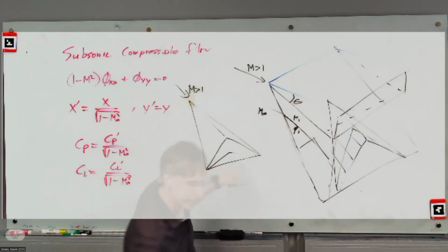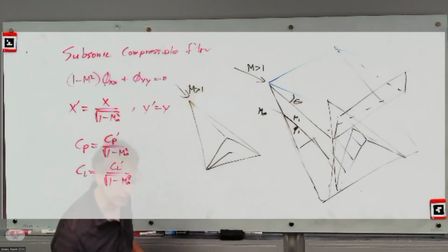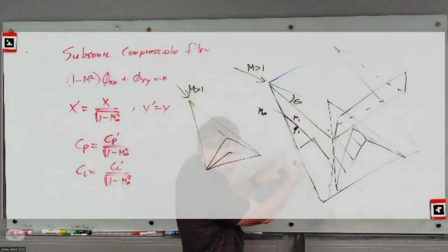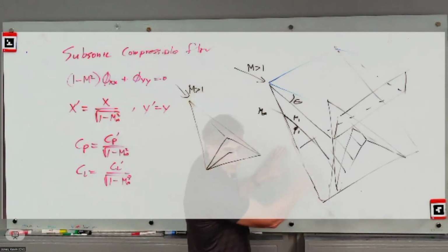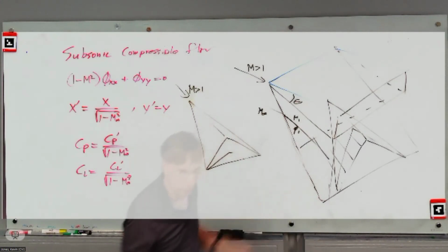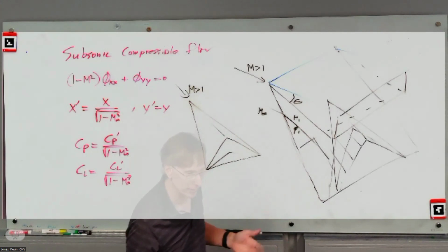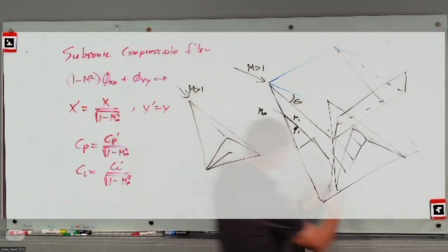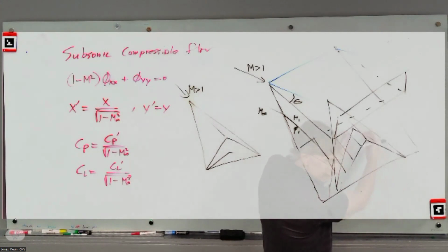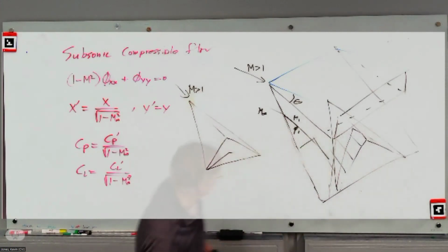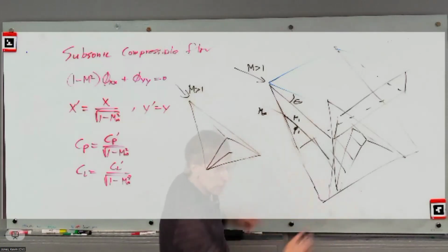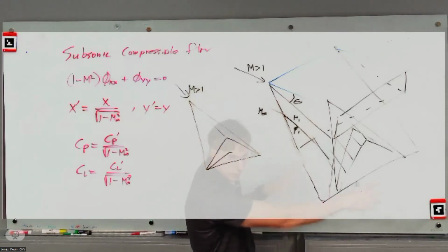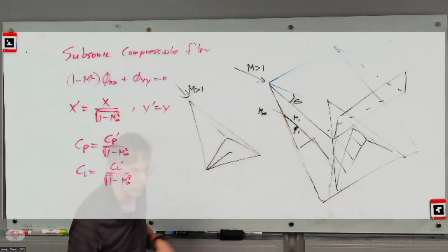The design technique we call sort of an inverse design. You start by knowing what the flow looks like. And then what you do is you plot the way streamlines go through it. And then, much like we've been discussing with potential flow, a streamline for inviscid flow can be a body, right? Can represent a body. So now I have this whole family of streamlines that I figure is the lower surface. To get more elaborate, instead of a wedge, make it a cone that generates a conical shock. Same thing. You have streamlines that pass through there. They're not straight lines anymore. Gets a little more work.